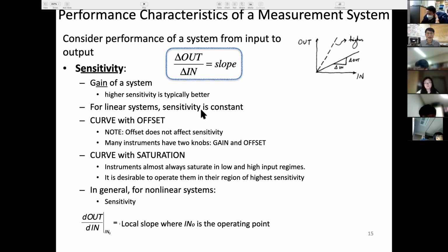But remember, whenever you measure something, there's always background. For example, when you're taking a picture in your laboratory, let's say fluorescence imaging, the background is supposedly black. But in fact, if you take pictures with a certain amount of exposure time, the background will never be black, okay? So that we call an offset. So in reality, the y-axis or the output level many times will not be zero when there is supposedly nothing as an input. So this we call an offset.